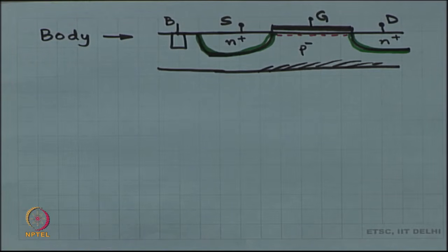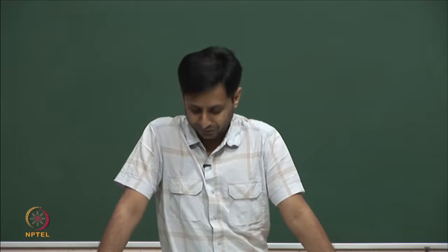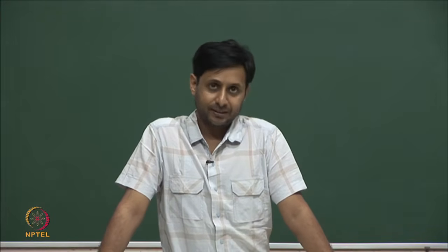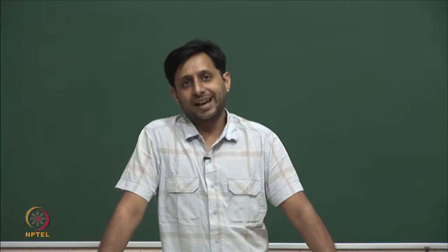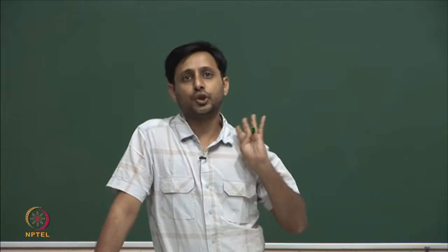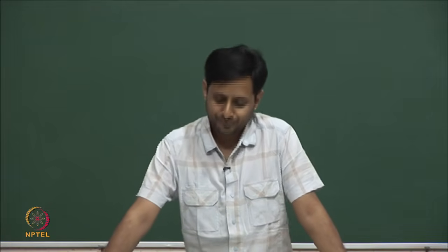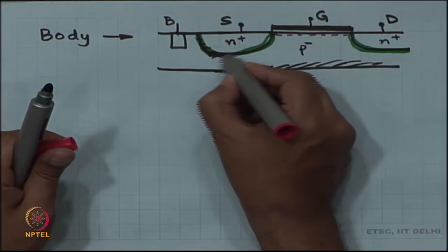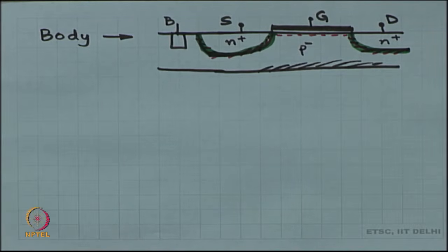That is the connection between source and drain, right, that is called the channel. So, that is how the MOSFET operates. It does not operate like a BJT. What is very important is to make sure that, unlike in a BJT, in a MOSFET these PN junctions should not operate like diodes, they should be reverse biased. It is very important. So, we have to make sure that these PN junctions are totally dead, not forward biased at all.